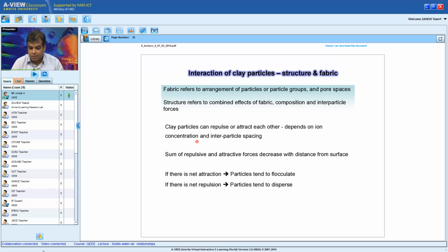Okay. So let's look at this. We say the clay particles can arrange in two manners, broadly. If they have a very strong attractive force, we will look at this again later. If the clay particles have less available water, they will have more attractive force because the negative charge is not fully developed.